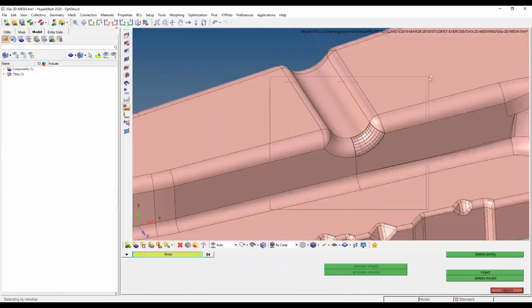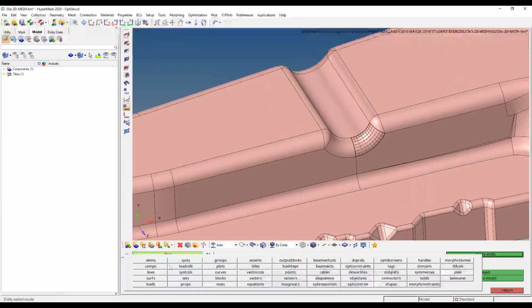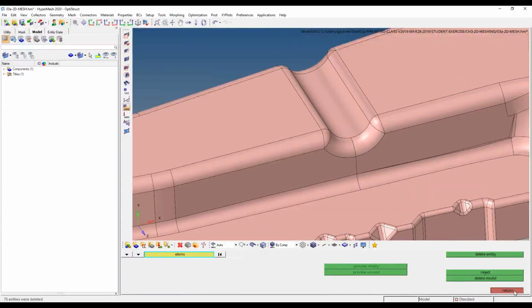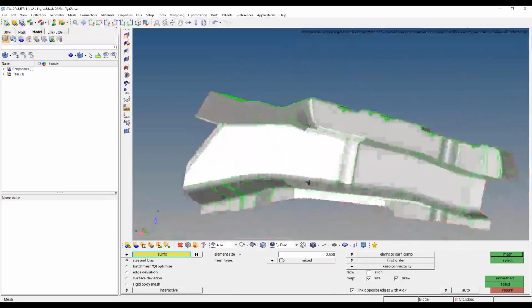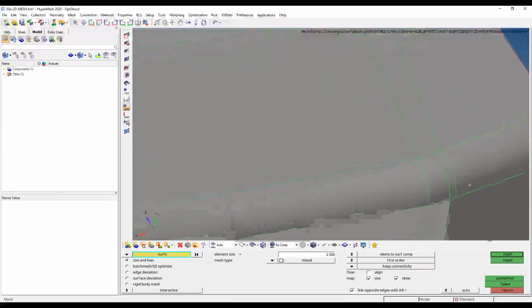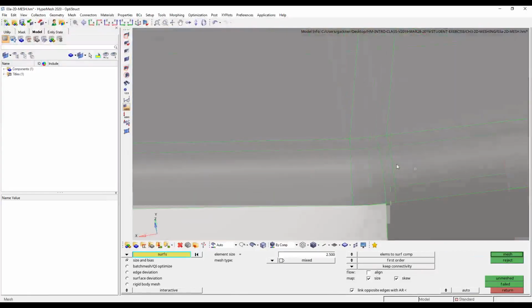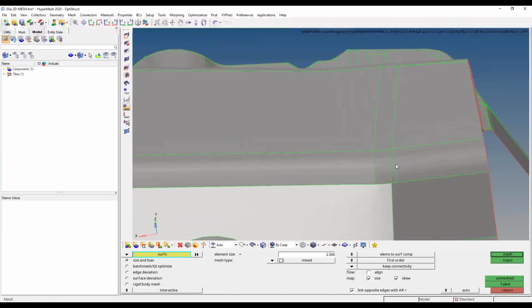So we're going to learn another trick and then combine it with that AR trick we just learned to make meshing a lot of our surfaces really easy here. So I'm going to come back to my back side of the part here for a moment. And some of you have probably noticed here that HyperMesh could be a lot quicker to use if you had less surfaces. As you start breaking things up into more but smaller and smaller surfaces, that's more individual surfaces I have to go through and mesh on my own.